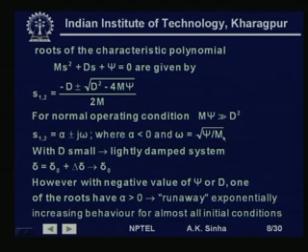So, with d small, that is for lightly damped system, delta is equal to delta 0 plus delta delta, finally leading to the same delta 0. That is, what we are trying to say is, if the system is operating initially at delta 0, we somehow give a perturbation to the system, that is, we make a delta delta change in the rotor angle of the system.